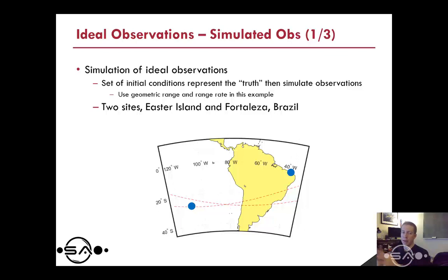And all the elevation mask does is it says, okay, from 0 to 5 degrees, or from 0 to 10 degrees at this azimuth, or this direction that I'm facing, I can't see the satellite because there's something in my way. And so in this case, the satellite's below the horizon for pass number 1. It may be within that 0 to 5 degree range, but there's a pretty good chance that if we're looking out from that ground station there's going to be something in our way, and so we're going to get a very poor pass.